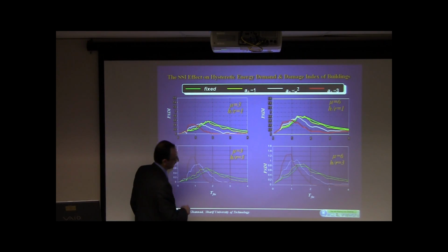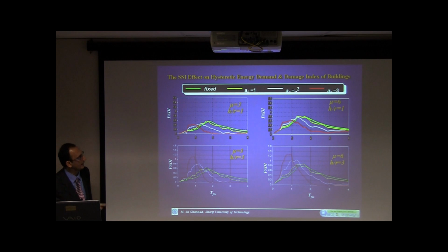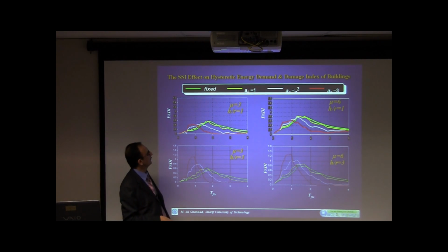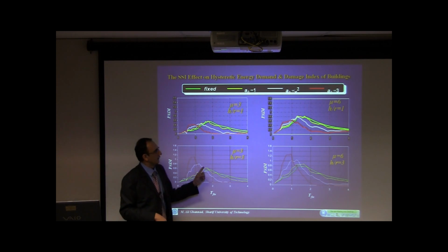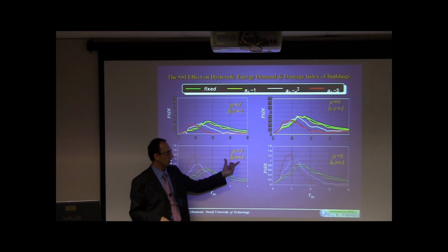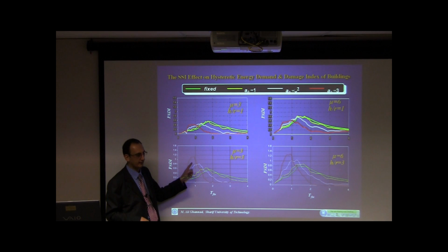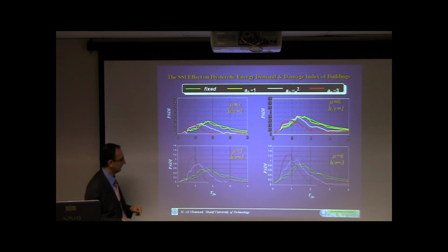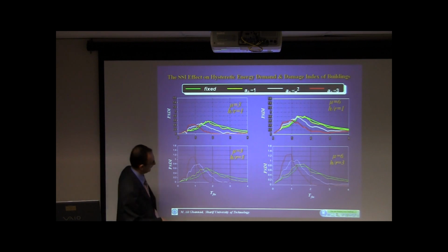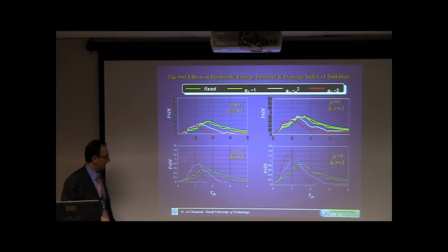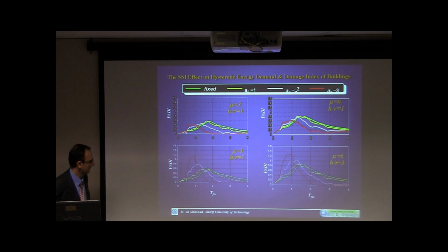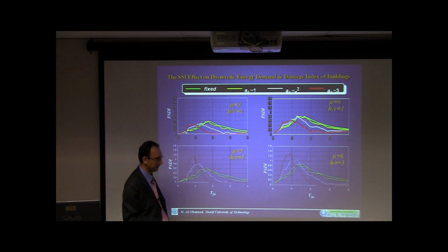Here we have the period of the fixed base structures, again for 3 cases compared to the fixed base structure. And it can be seen that especially for slender structures, one may expect much larger damage indexes for the soil-structure systems compared to the fixed base structures. But maybe this graph seems to be very, I'll say, scary.